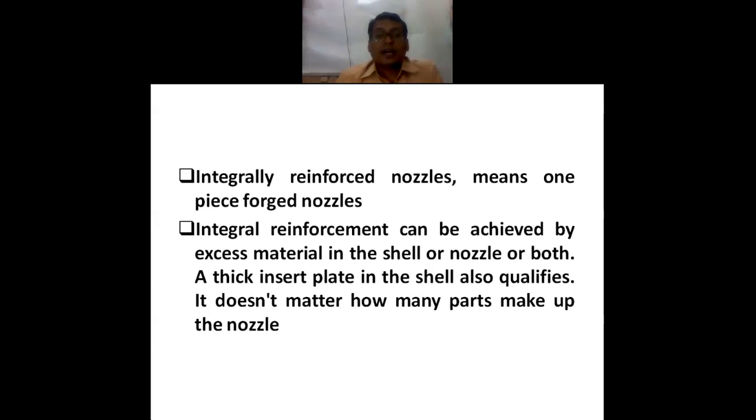Then there are integrally reinforced nozzles, meaning one-piece forged nozzles. Integral reinforcement can be achieved by excess material in the shell, or the nozzle, or a combination of both.